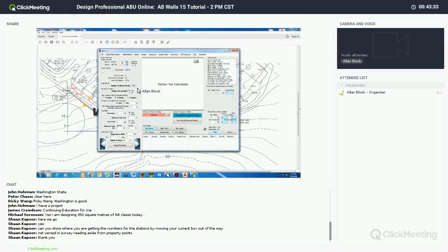Now, below this, we have our geogrid information. This is actually where you're going to start doing all of your decision making. Based off of the new industry push for zero wall failures, we have an initiative out there for best practices, which is a document based off of testing and industry experience for the past 30-some years. And based on best practices, it has been determined that you use grid when you can. It's a relatively inexpensive insurance to a wall design. It's easy to add. In the scheme of things, it's not that much of an added cost. But with that being said, we do have that option to do a gravity wall without geogrid, depending on site constraints or whatnot. You do have that option.